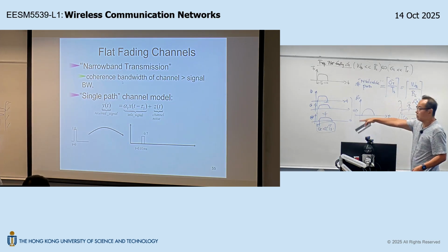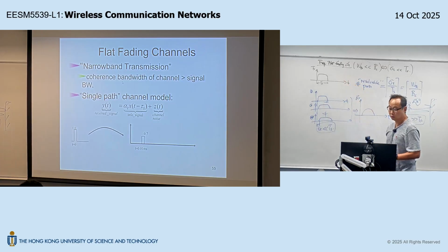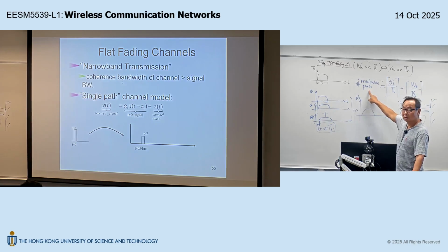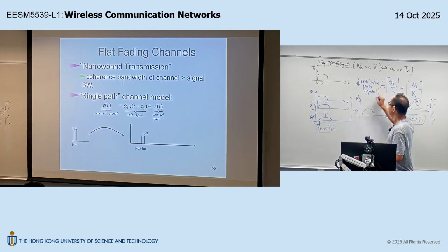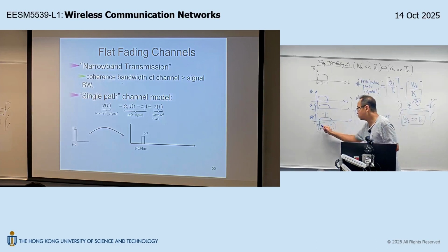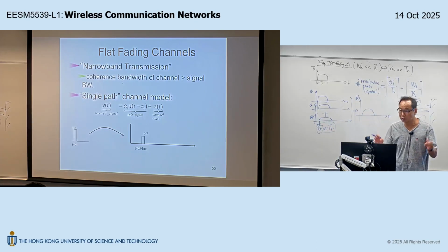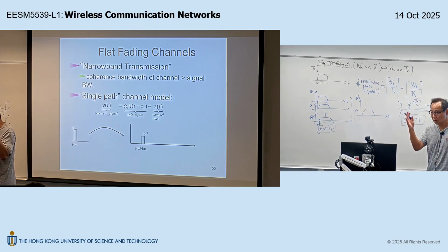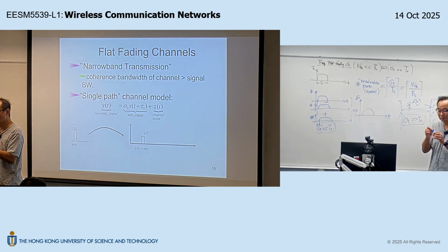So in this first situation, frequency flat fading channel, you only have one resolvable path, or one resolvable symbol. Now, although you have one resolvable symbol or path, somebody calls it symbol, the actual number of physical multipath is still plenty, okay? So once again, you still have 1,000 physical multipath behind this one resolvable symbol. It is just that the delay spread is much less than your symbol duration. So you cannot resolve these 1,000 paths as individual paths, okay?